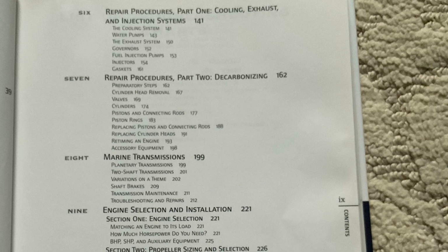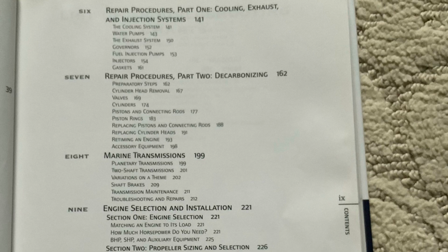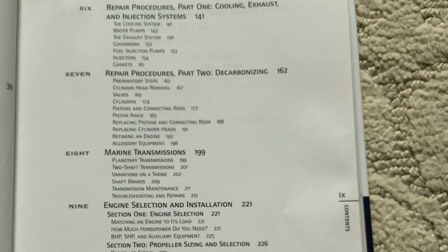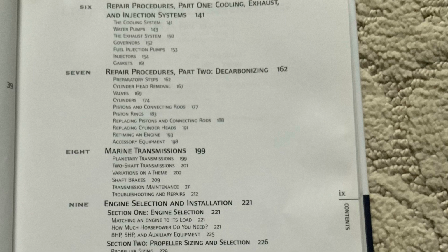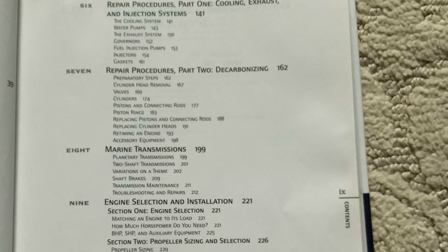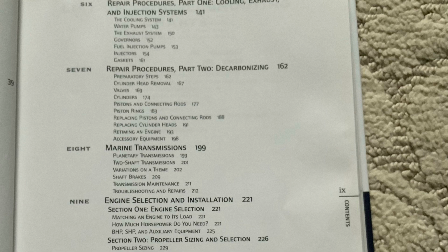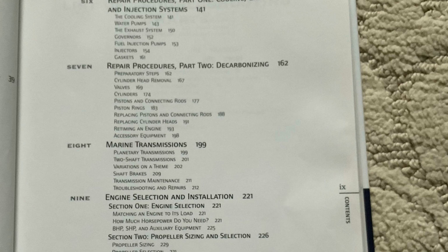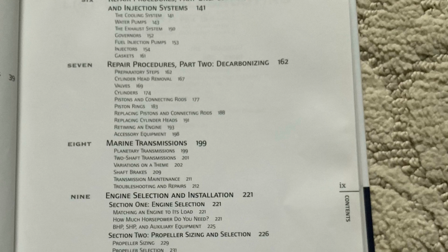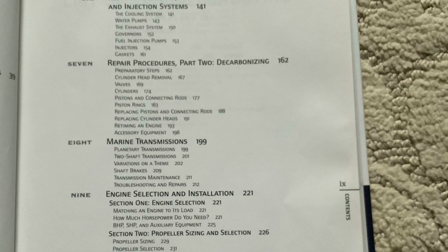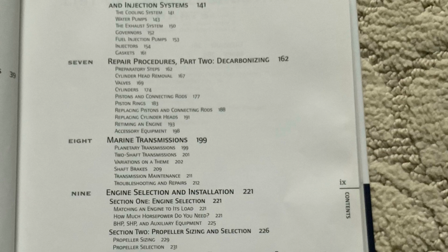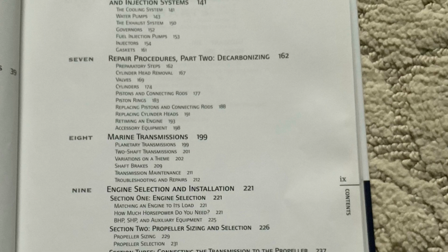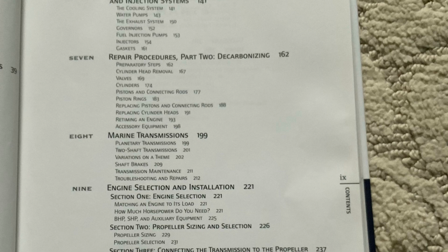It is possible to calculate the heat content of the fuel by measuring how many BTU, or joules in the metric system, are produced by burning a given amount, such as a gallon or liter. An engine's horsepower, HP, rating, or kilowatt in the metric system, can be converted to BTU or joules. For example, 1 horsepower equals 2,544 BTU. In this way, the heat energy going into an engine, the number of gallons or liters burned per hour times the BTU or joule content of the fuel, can be compared with the power being produced by it.